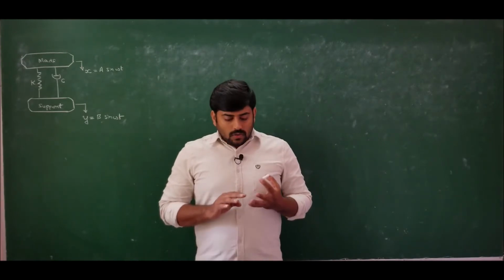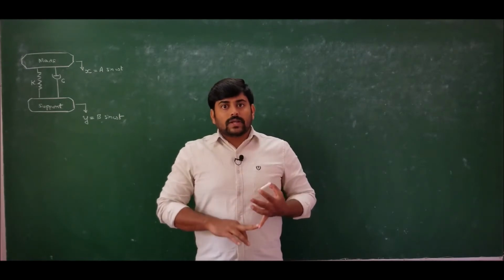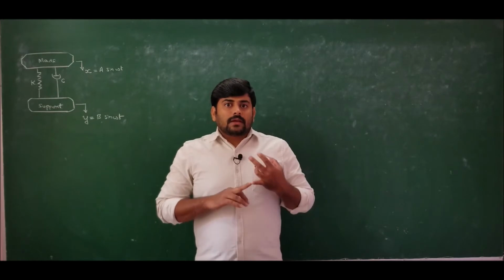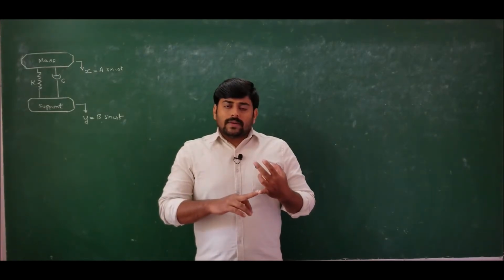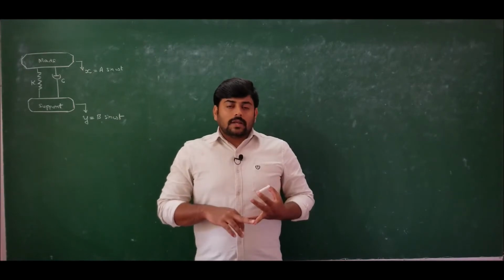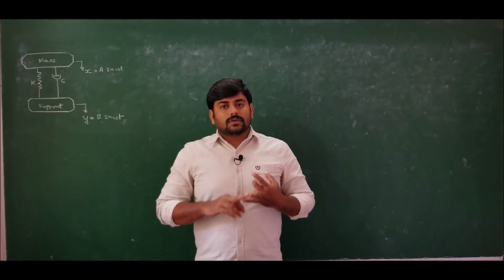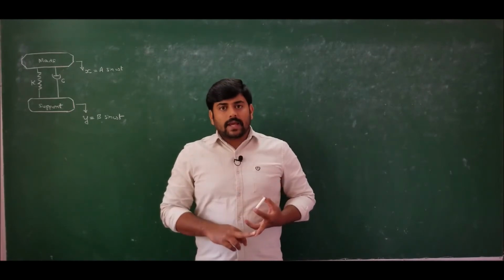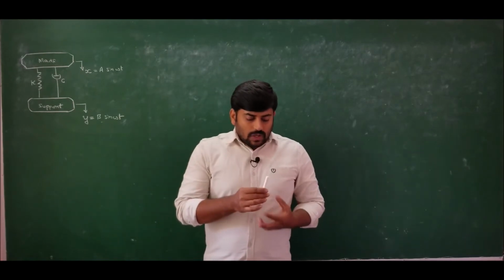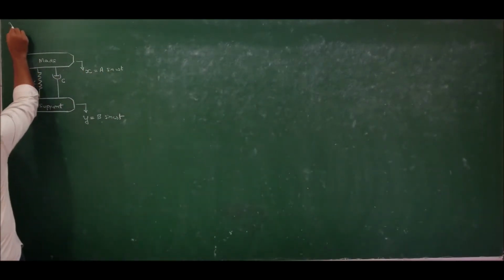So rubber can be used as a very good isolator when shearing loads are transmitted from the vibrating object to the foundation, whereas cork can be used as an isolator when compressive loads are transmitted from the vibrating object to the foundation. Spring can be employed in all working conditions. So what we have discussed so far is vibration isolators.